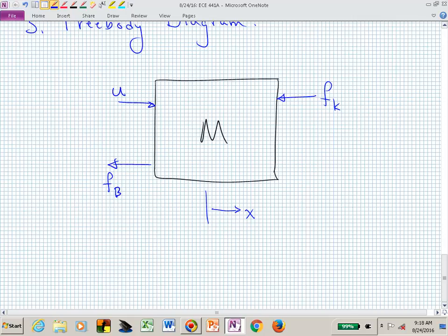Meaning, if I now tried to move this mass to the right, it has some inertia, doesn't it? And what direction is that inertial force directed in opposing that movement? If I try to go to the right, is something opposing that movement? Yes, it's the inertia of that mass, irrespective of the spring and the dashpot. That mass has some inertia and it opposes that. And so since it's what I'm calling an inertial force, I'll call it F sub I, opposing that movement in the positive direction.